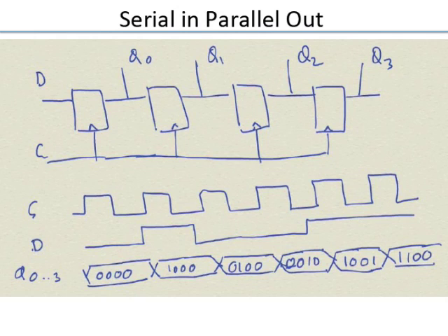Right? For example, if an AND gate doesn't have a connection to VDD, then when you give a 1-1, you will never get a 1 out, because there is no connection to VDD, it will never pull it up. So you can check that by putting 1-1 and checking if the output goes to 1. If it doesn't go to 1, you know there is a problem. So like that you can identify test patterns.